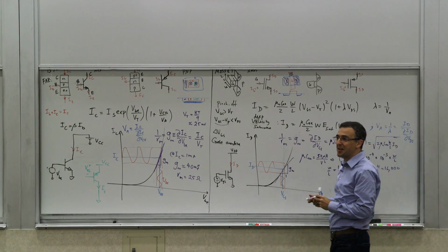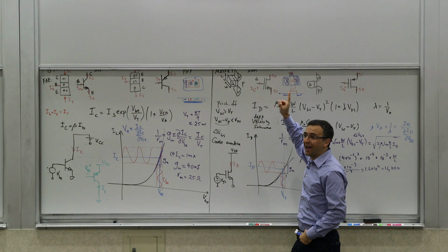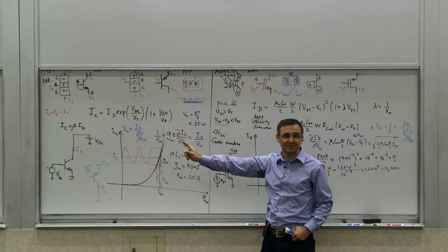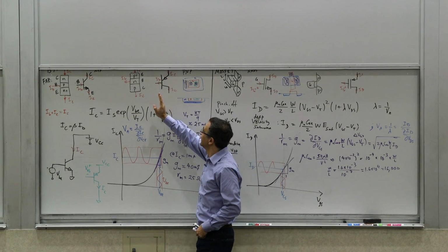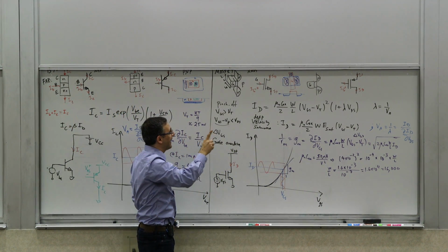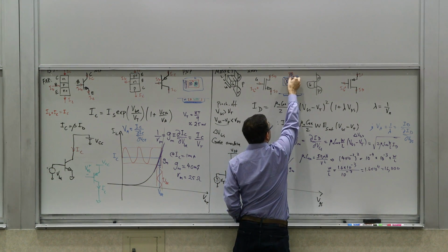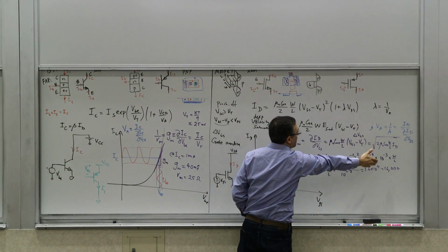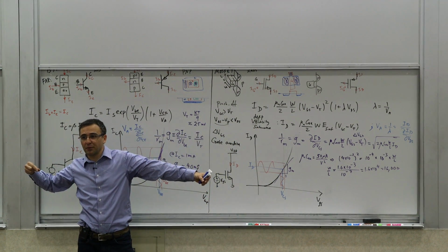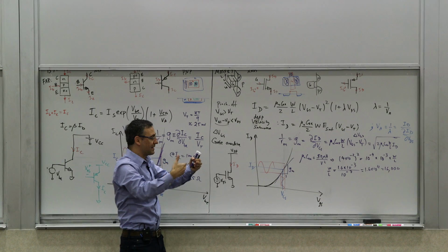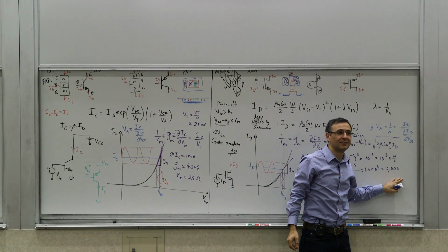So that means that for this transistor to have the same GM at the same bias current as this guy, it needs to have a ratio of W over L, where this is L and this is W, of 16,000. Of course, you don't make it out of one incredibly long and thin finger. We make them out of multiple fingers. But that's still a lot.